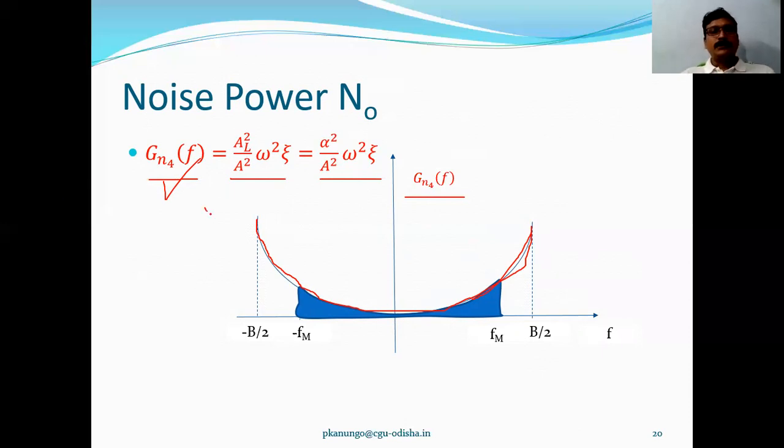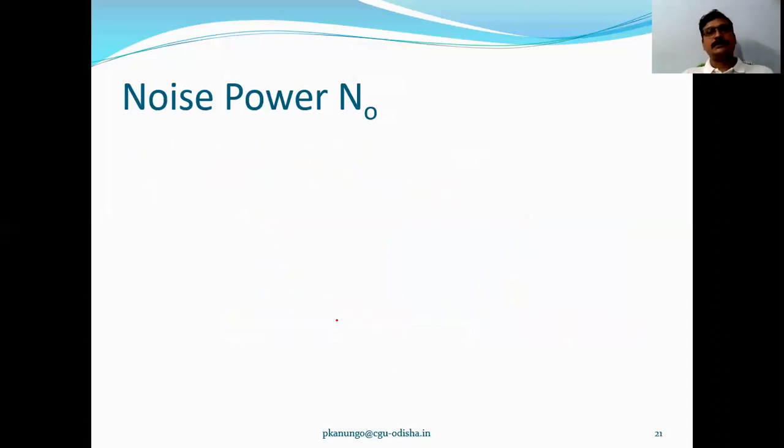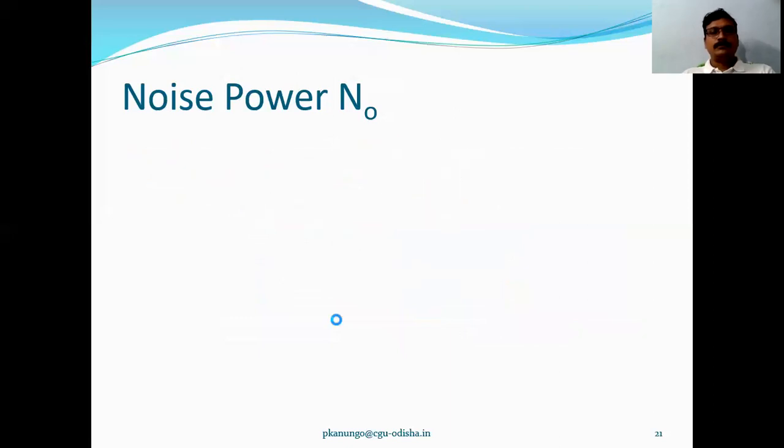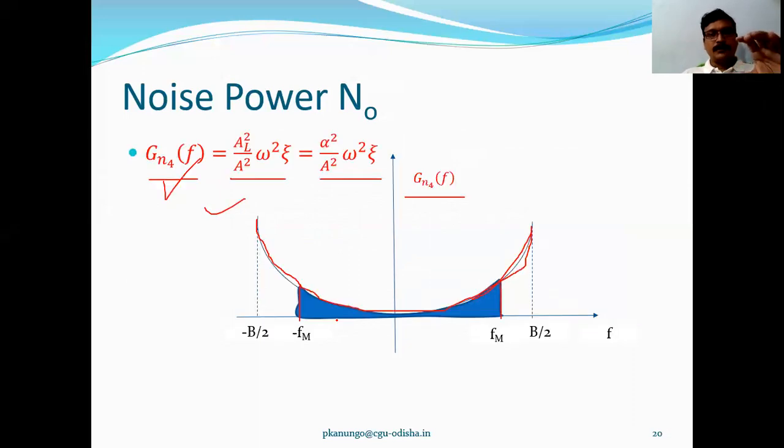So when you pass this through the baseband filter, the baseband filter frequency is equal to fm2 minus fm, because it is a two-sided power spectral density. So only this portion of the power spectral density will pass, because the filter is ideal. We are assuming the gain is equal to 1. If we assume the low pass filter characteristic is like this, a constant fm2 minus fm, and we pass this kind of power spectral density through it, then we only have to find the area between minus fm to plus fm. That area is the output of the baseband filter.